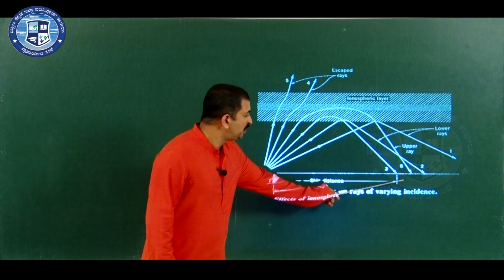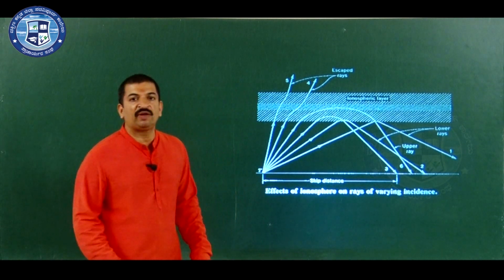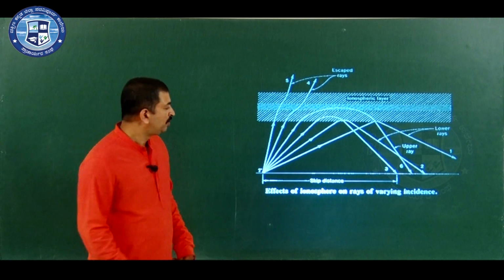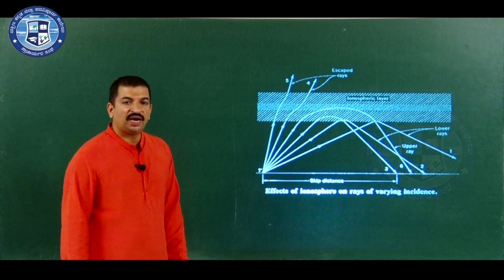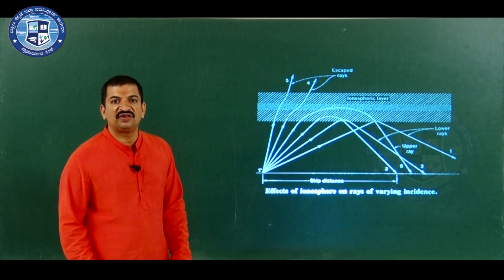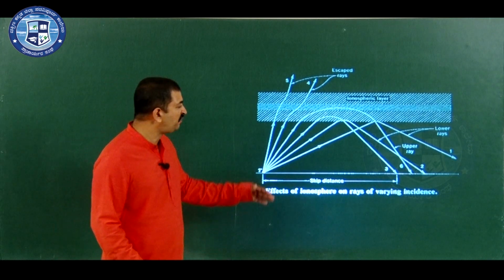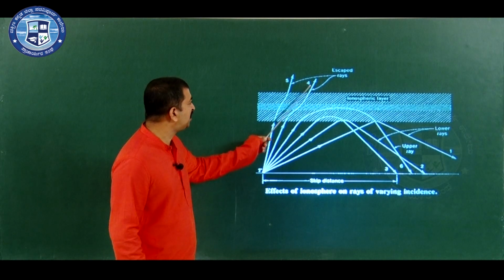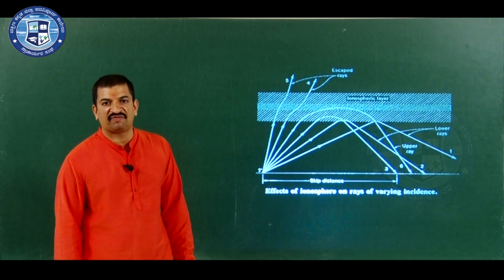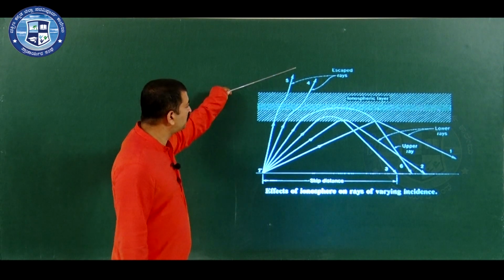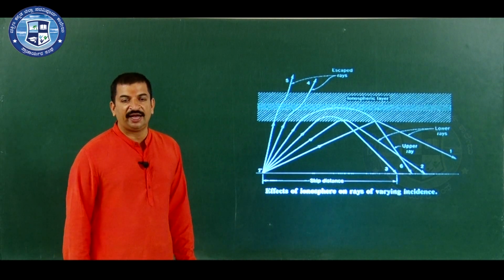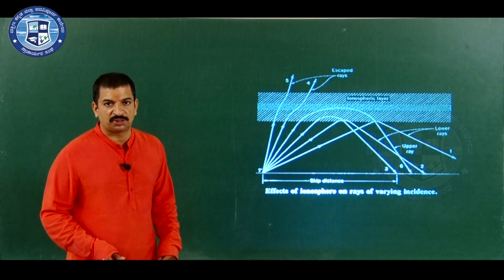Now, ray 3 is the first skywave which is received. Now, let us reduce the angle of incidence further. If the angle of incidence is reduced further, as in the case of ray 4 and ray 5, the ray will not be returned down to earth; it simply escapes from the earth atmosphere and hence the energy is lost.